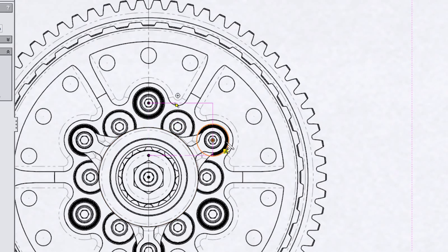The last or third selection is where it's really powerful. Again, we can snap to geometry, and in this case, I'm going to choose to create a cut through this fastener, and there's actually a bushing there as well. And I'm going to go ahead and select that, and as soon as I do, SOLIDWORKS brings the pop-up menu back, but it creates the jog in the section line for us. Let's go ahead and take a look at the next option.